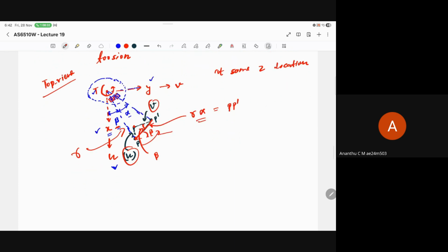As alpha changes from bottom to top, you are going to have different twist angles, and because of the different twist angles from bottom to top, you are going to have different values of u and v. So displacement u, which is a function of x, y, and z, is this: we know this angle is beta, and we know this distance P prime.